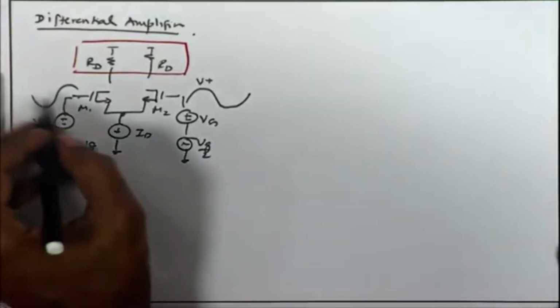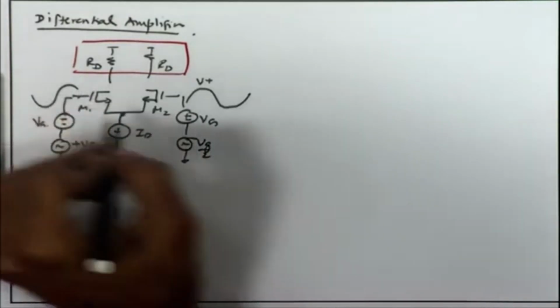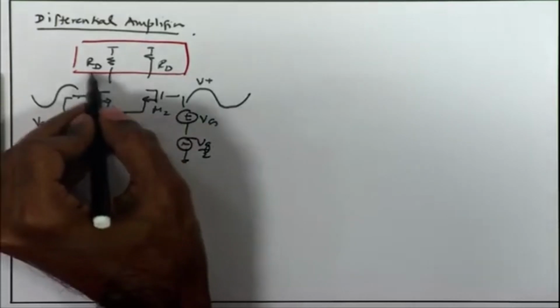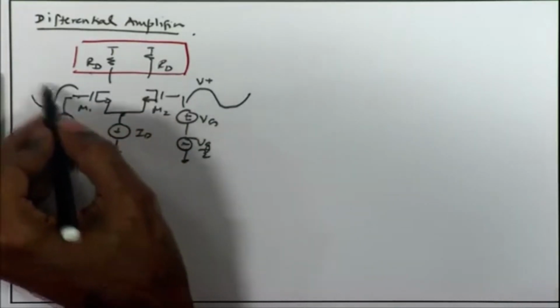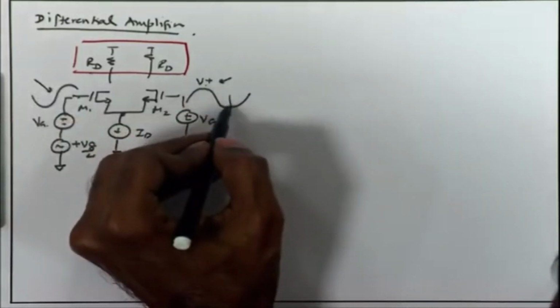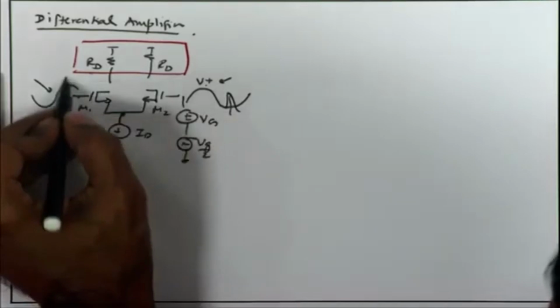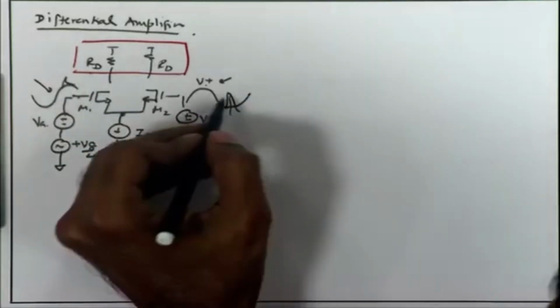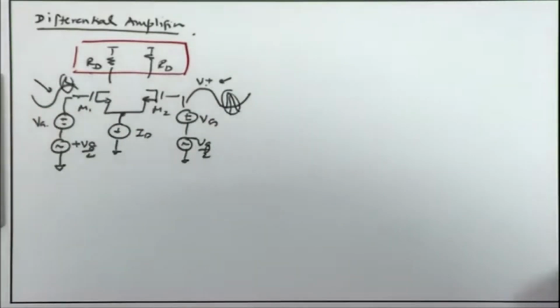These two differential signals are going to produce a corresponding differential signal as the output. Any common mode signal that comes in, suppose at a particular time instance there is some disturbance, a kink on both sides, ideally a differential circuit should be able to reject this kind of common mode disturbance on the input signal. That is the advantage of a differential circuit.